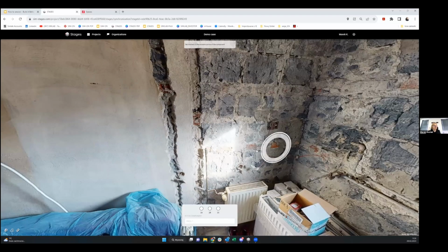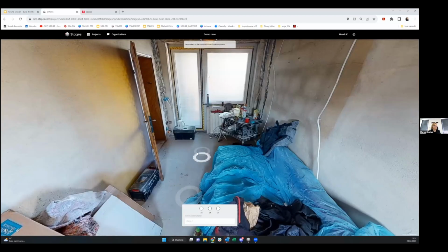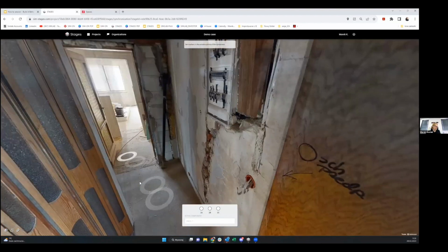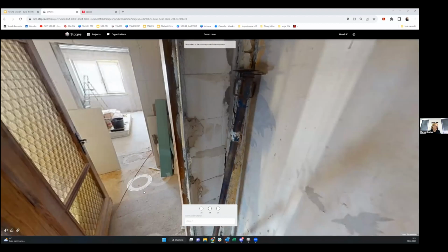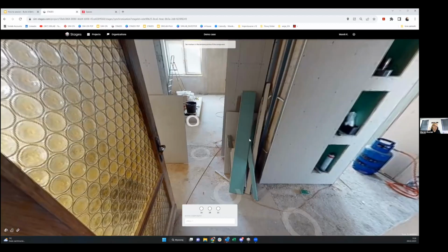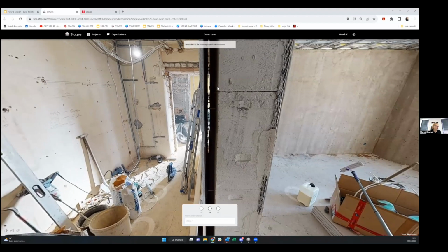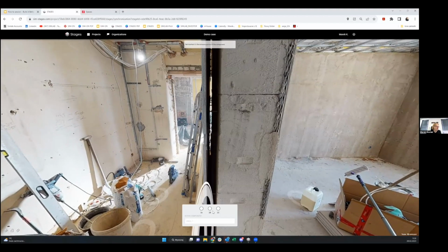And as you see, we are not in the same position. So we need to point to the system the exact same points in the Matterport space that we were using as the calibration reference points. So you see, it's now showing 2A, 2B, 2C, to synchronize it with the previous model. Because I have a big resolution, it shows that that was here in that corner. So I know that this is point 1A, which is equivalent to point 2A in this moment.